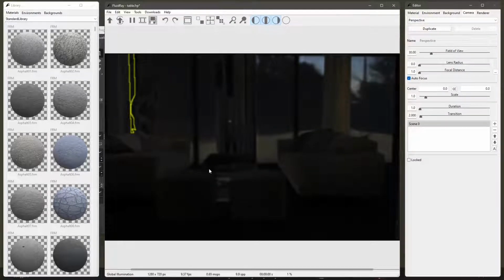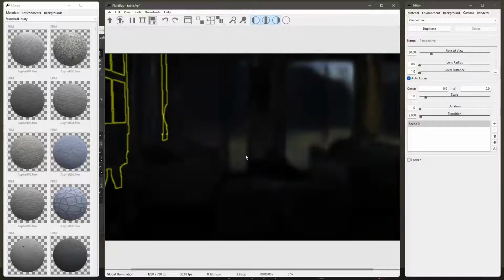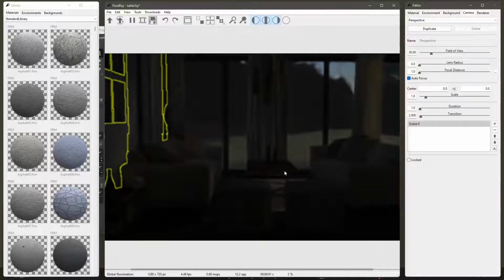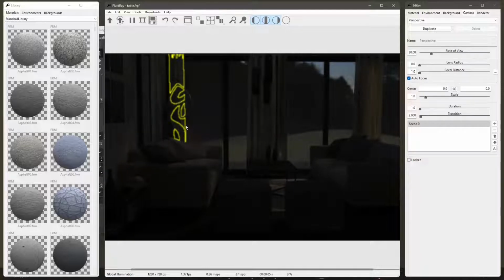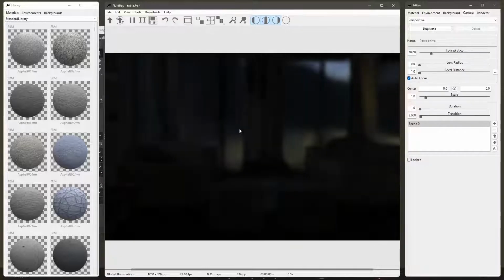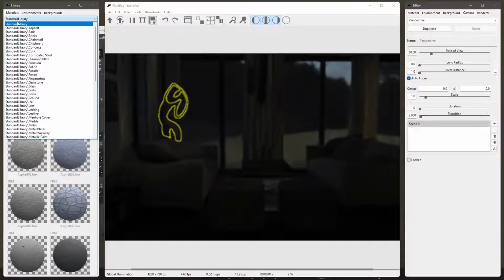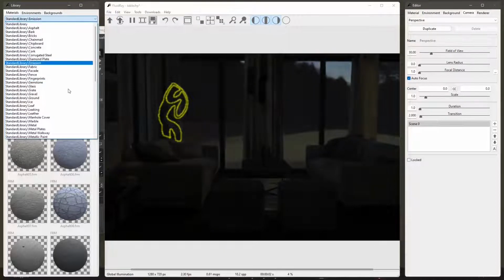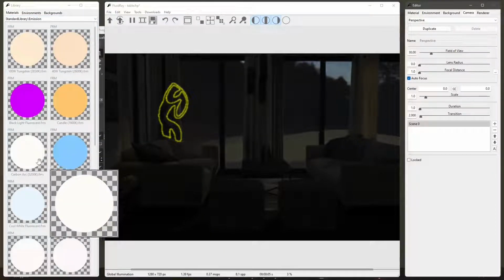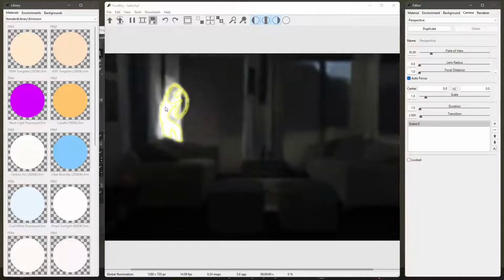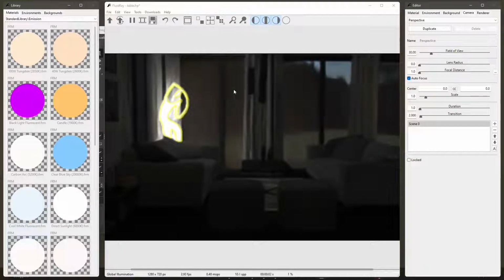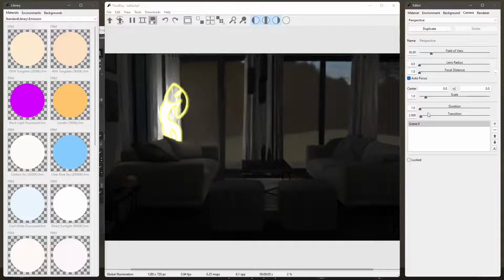Now in this case, we want to focus on the geometry, on the model, and on more complex scenes. So these are really complex scenes because they have furnishing, they have furniture, interior. You can see there you have some sofas. Now, if I click and drag an emissive material on that statue there, that statue is going to become a lamp and it's gonna begin to illuminate my scene, to lighten up my scene.